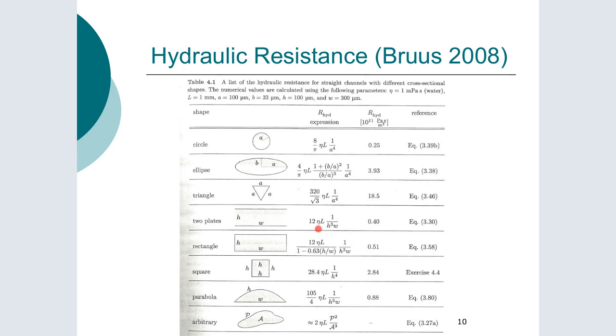So we can see that there's always just a viscosity present, there's never a density present. And again, that's because the physics of this is dominated by viscosity. So it's a pressure-viscous balance that you're dealing with. So you don't have any density terms inside there, so there's no Reynolds number in this. And we discussed that before in class in one of the tutorials.